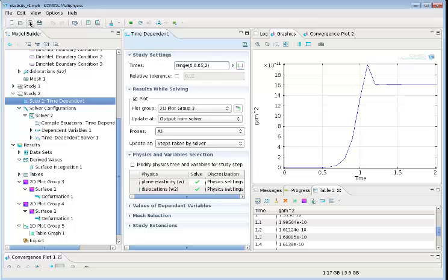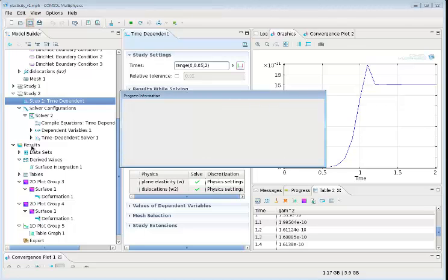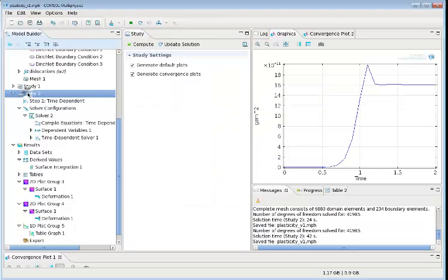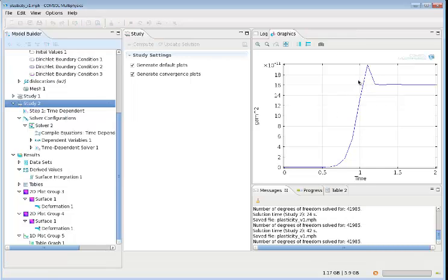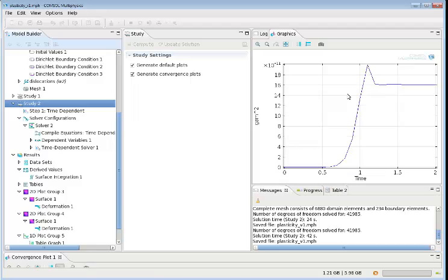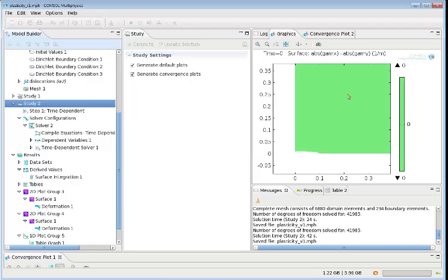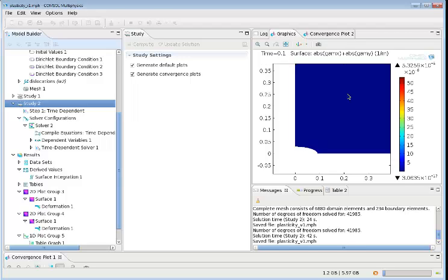Remember, I'm using a strict time step because COMSOL has its own internal time step where it tries to figure out how to step forward in time. Remember, there's critical time steps where things can go unstable. I'm putting that in as a fixed value, so you can continue reducing that if you do see an instability. So let's see what happens here. Let's see if the result will be any different.